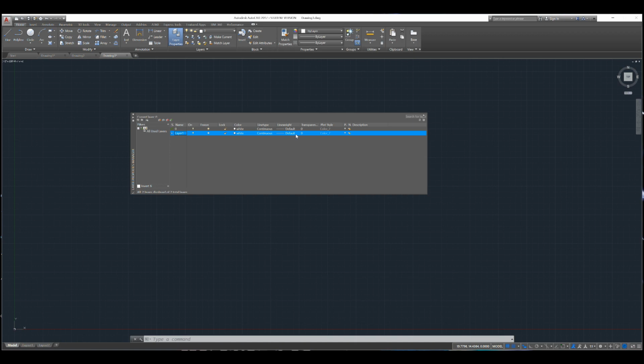So if you were to get this drawing and you were actually going to be manufacturing whatever part is drawn in there, you wouldn't use those lines as part of the design. They're more to help you determine where the center of a hole or a cut is and things like that. So sometimes we need to have multiple layers. Usually all of our drawings are done in layer 0 and layer 1. And then a lot of times we have hidden lines in another layer, probably like layer 3.